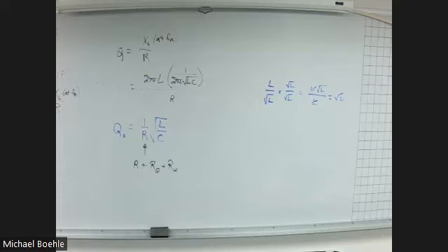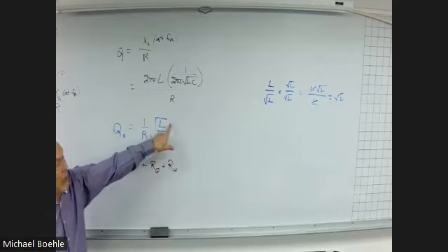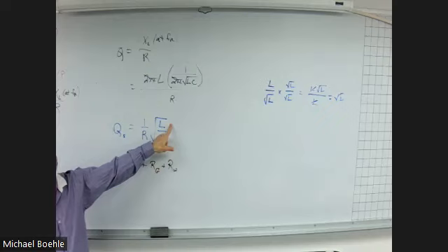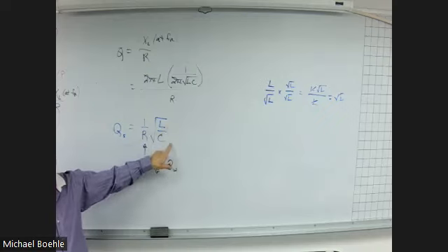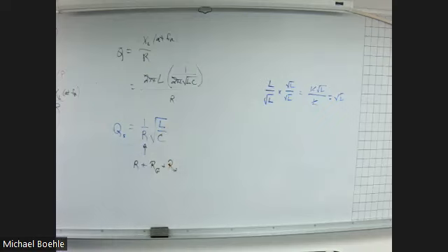So you can look at a simple formula like this and just say, all right, a bigger inductor, higher Q. Smaller capacitor, higher Q. So you can see that relationship fairly easily. But what do we know? We know that the bigger our inductance, the more resistance it's going to have, right? The more winding resistance it's going to have. So you're kind of fighting against yourself somewhere. So, all right. Does that make sense to everyone?